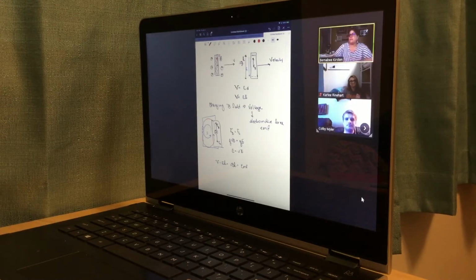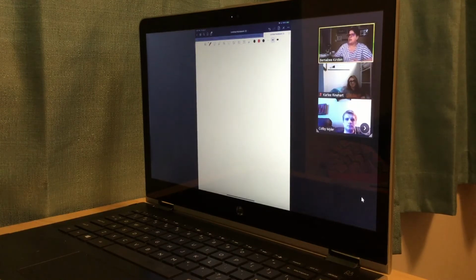Yeah? All right. So we have an example in the notes. Example 1, we want to compute the motional EMF and the current in the circuit for the following. So we have a conductor that has a length of 0.1 meter. This guy has a velocity of 0.1 meter per second. We're going to ultimately connect this to a resistor of 0.01 ohms. Our magnetic field is going to be 1 Tesla.